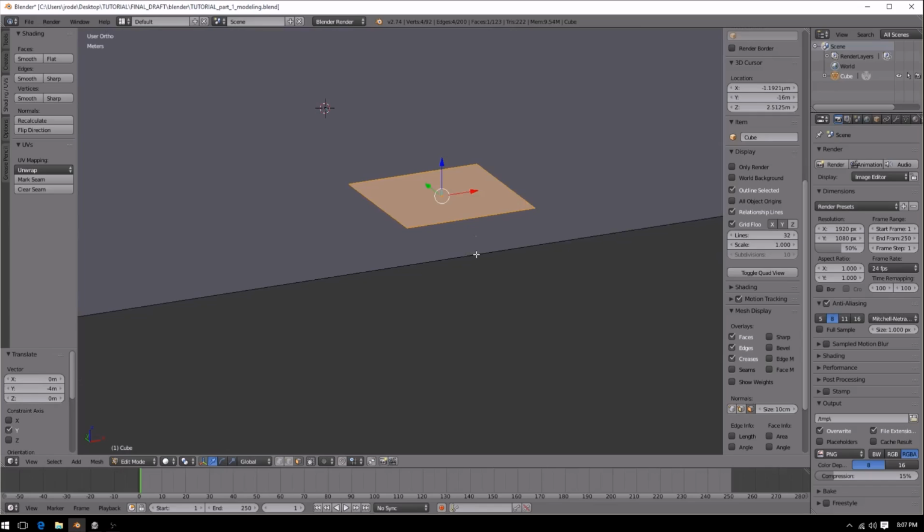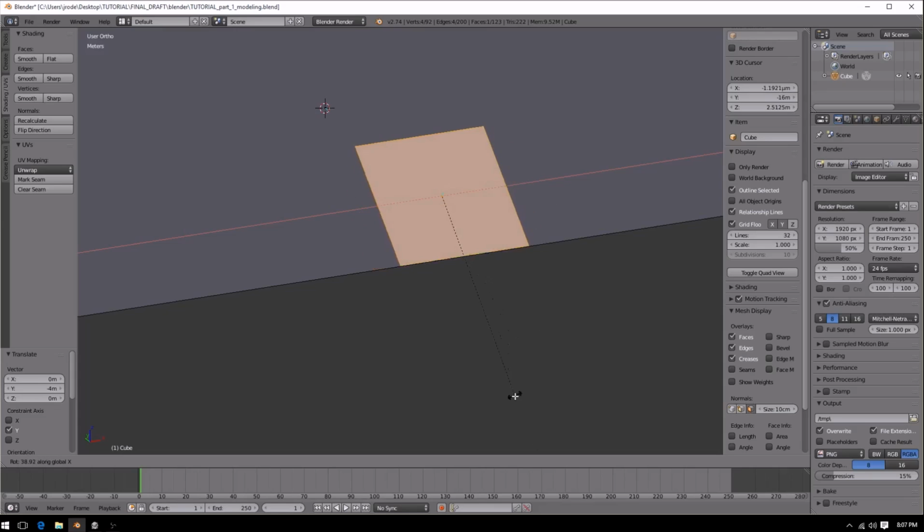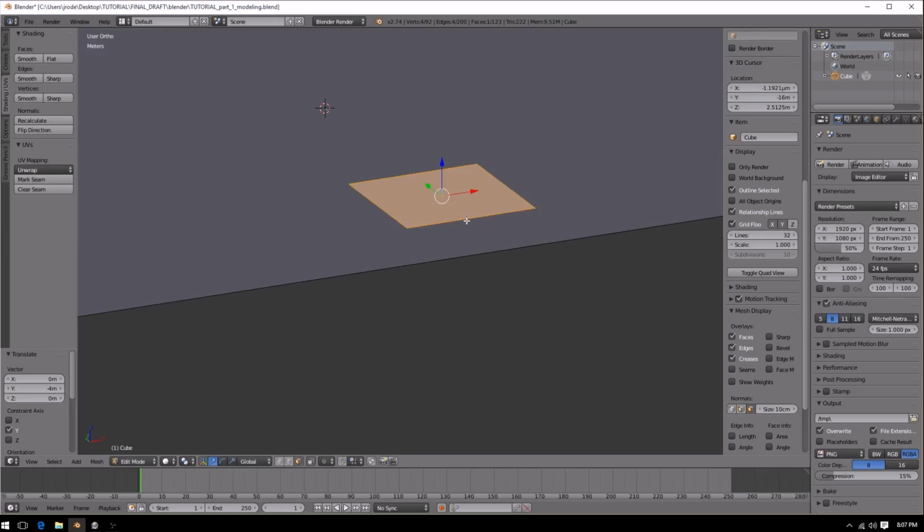When you rotate something, these axes are almost like pipes or very thin pieces of whatever, and think of this plane as resting on that. Anytime you rotate this, it's going to rotate as if it was balancing on that pipe. So for instance, if I say R X, we can rotate it this way. Notice how that red line will appear to give you a guideline on what axis you snapped on. Another easy way to move this is, remember, this is kind of like a crank, so turn it in clockwise and counterclockwise motions, and you'll get this to move real good.